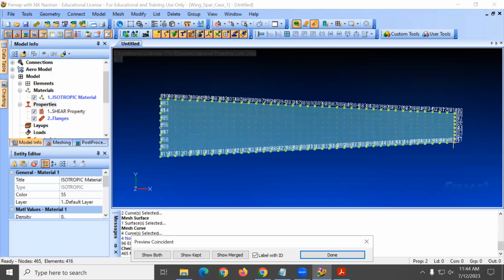You need to connect all the flanges that we put around to the shear panels, no? Yeah? Can you repeat that last step? You said, Tools, yeah, check, but it's all the way down. Coincident nodes, select all. I'm on preview, so that makes sense, no? Now we are connected all those flanges, no? That around to the shear panels. And I guess you can click done.